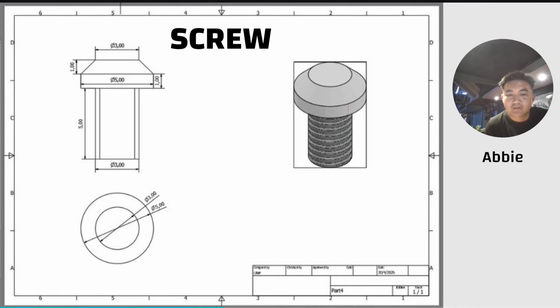The tools and technique that I used: I used the revolve command to create the screw body and head profile. For the technical detail, I used the thread tool to apply standard metric specification. To create the cross for the screwdriver, I used a sketch on the top face followed by an extruded cut. Because there are two screws, as seen in the quantity list, I used the pattern tool in the assembly environment to ensure they were spaced perfectly apart without having to constrain them individually.